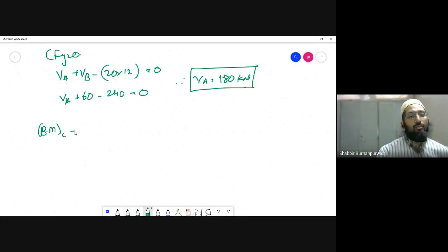Okay, we take bending moment at C, and because it is an internal hinge, we know that bending moment at C is going to be 0. There is a difference between summation of moment at every point, which will be 0, and bending moment, where we consider the left hand side or right hand side of that particular part. That is going to be 0 only if it is an internal hinge, for any hinge position or condition.